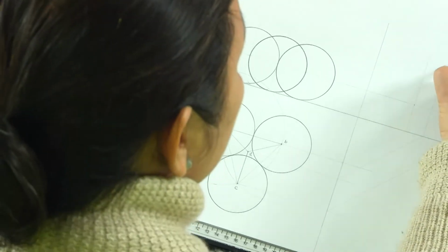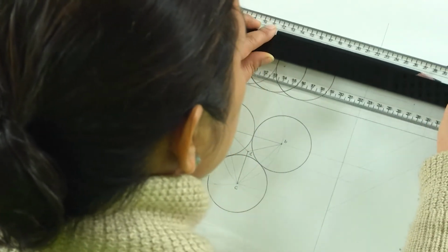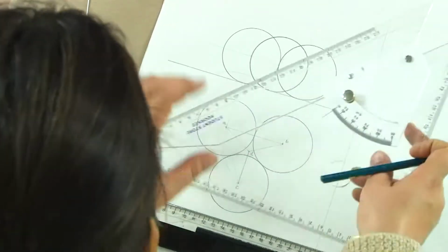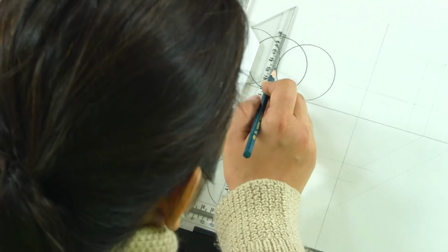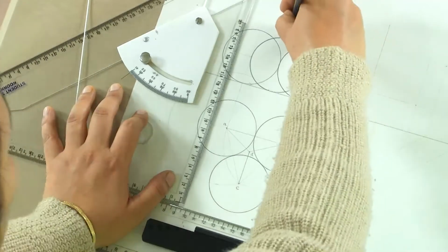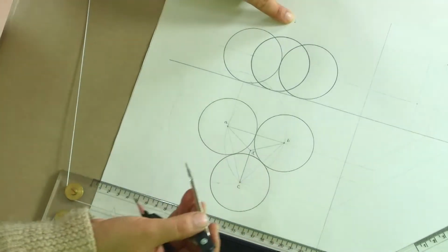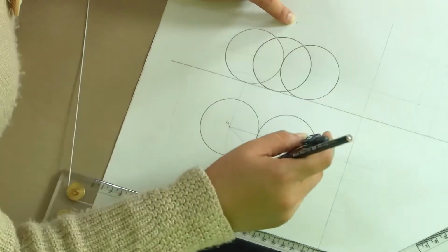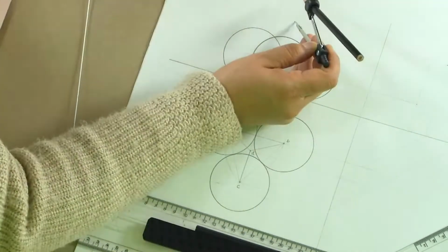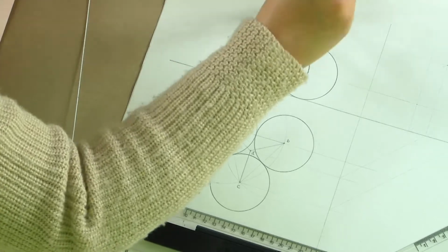So, we have now got this point D in height, and we will not make spheres here, we will just take it to the VP, and from here we know that D is going to lie here. If you match the orthographic projections, this is the point D. And now, if I have to draw this sphere, since I know the center here, I will take the same radius and draw this another sphere.